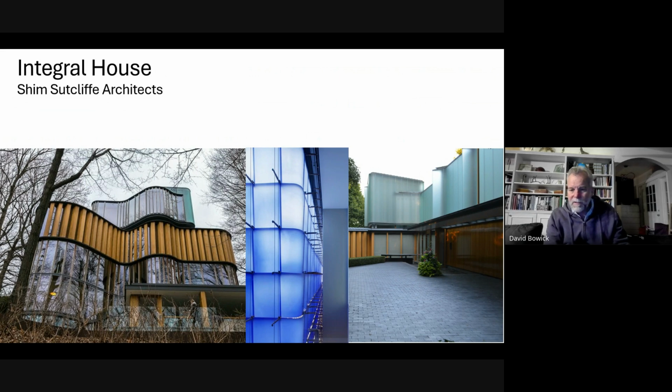And then the image on the right, this is the most interesting thing to talk about today. This is a glass scrim. The upper part is a glass scrim. Glass fins bolted to the back of the house, and then glass adhered to the glass fin using very high bond tape, VHB tape, very high bond. This is the same tape that is used to hold the windshield on your car.